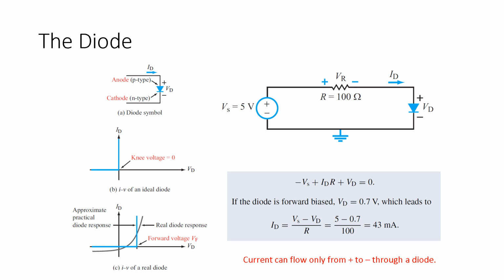If you look at C, you actually get the real diode here. And the real diode is going to be that curved line. And so that curved line is actually saying that there's thresholds in this diode, we're going to talk about LEDs in a minute, which means that current kind of increasingly flows the more voltage you get up to the point where essentially we have saturation, which is another term that we're going to look at soon. However, we can approximate this really well with that blue forward voltage there.